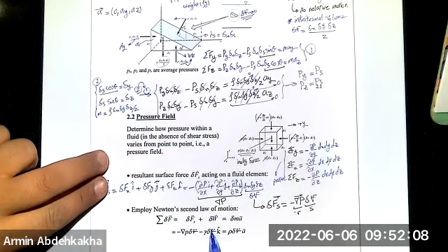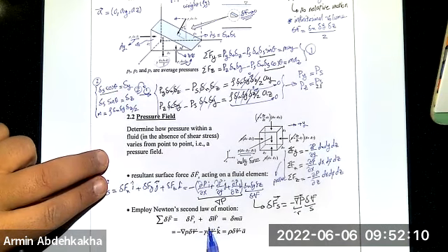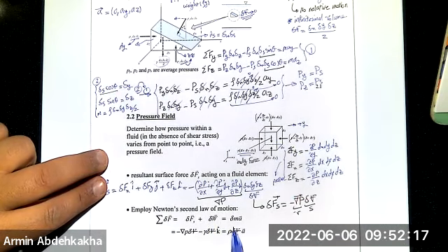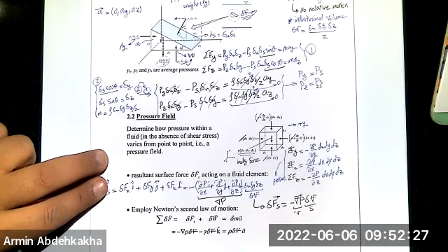But now we are going to consider the delta W, which is the weight of the fluid, right? And then finally we can write that the acceleration of this volume, treating it as a rigid body, is equal to surface forces plus body forces. The surface force, we proved it, is the gradient of the P times delta V, the volume. And what is the W?